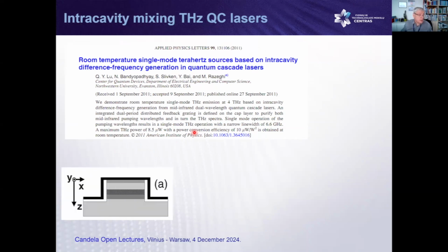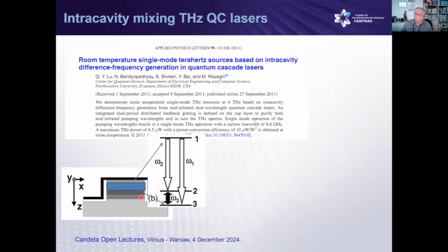And what they're doing here is making two lasers in this one, and they have interaction between artificially designed quantum wells, where the distance in the levels was selected so that two infrared lasers exactly mix in that, artificially, also called Chi2 in this structure. And so we have an intracavity mixing, two lasers in one laser, and it allows to emit terahertz. So it's room temperature.